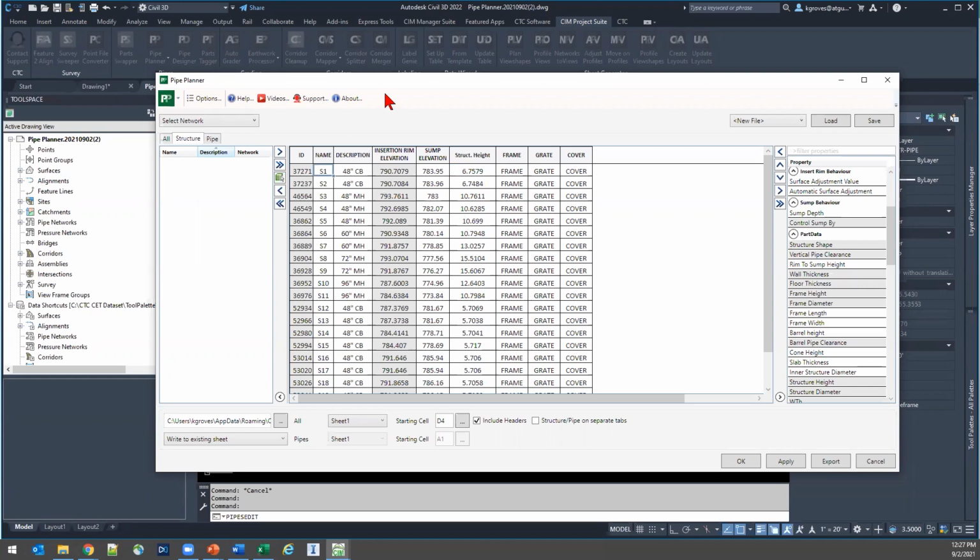So what else? We can also do those renaming or those part swaps in here. So I want to call this MH-1, call this MH-2. And now since these values, oh, those were catch basins, not this one, S2. So these manholes, if I change that to MH-3, MH-4, I can actually just select these first two. And now this drag drop in the bottom right, this is going to be applying the actual formula. So I'll go down to structure number 11, which is my manhole, and it's going to count those up for me for all the rest of these catch basins.